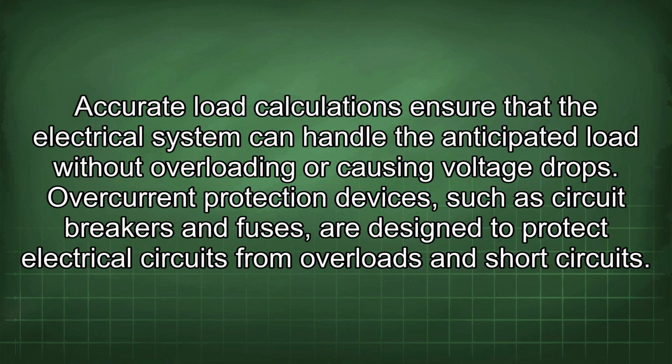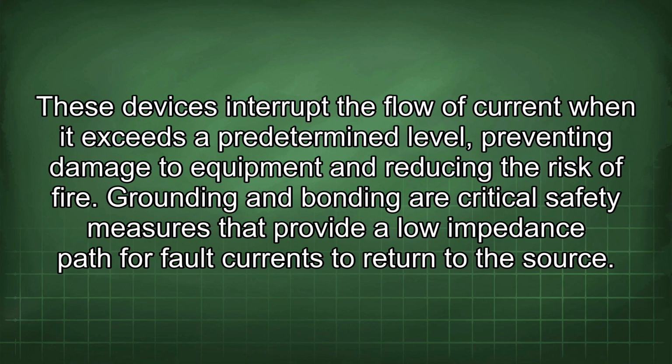causing voltage drops. Overcurrent protection devices, such as circuit breakers and fuses, are designed to protect electrical circuits from overloads and short circuits. These devices interrupt the flow of current when it exceeds a predetermined level, preventing damage to equipment and reducing the risk of fire.